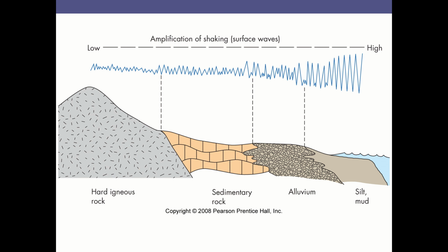So how is it relevant? We should know, for example, that's why we do soil testing. Soil testing can be done for two things. One, of course, we primarily do it to check what kind of piers and what kind of footings can be done. In addition to that, it can also give an idea of how strong our substrata is, and what kind of earthquake measures need to be incorporated in the building design or site planning and so on. So this is also relevant, and that's why the subject has been put here.